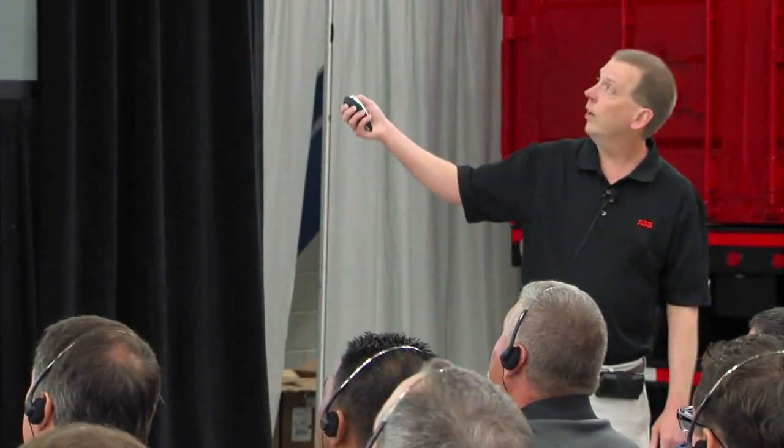If I'm running a fan, it probably isn't that critical. But if I'm running a conveyor line, I might need to know more exactly how fast I'm going so that I don't drop boxes off the end or not get them to where they're supposed to go. So this can tell the drive exactly how fast that motor is going, and then the drive can adjust to say, oh, I'm supposed to be at 900, I'm at 850, I better bump it up a little bit. So that's built in. That was the first evolution.